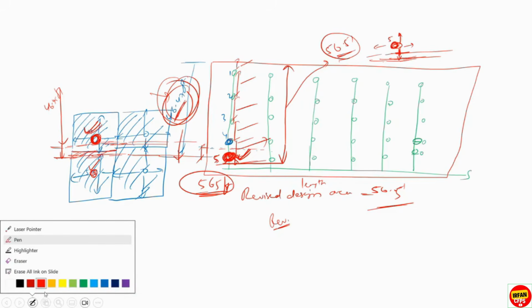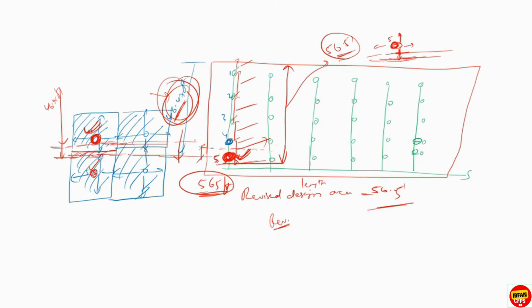Okay, so now from here you got like 56.45 design area. You make a rectangle here. You got the rectangle, so 5 sprinklers you already got. But how many sprinklers you need to consider, you still don't know, right? Based on this.